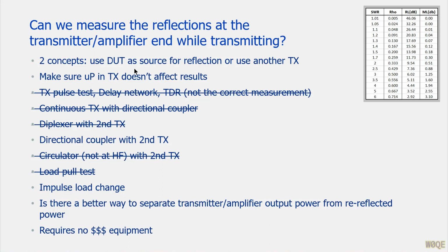And I wanted to do this without the microprocessor that's in just about every transmitter made messing with the output. Most microprocessors in transmitters are set to some limit. It might be SWR, reflected power. Usually it's reflected power, but I don't want the microprocessor messing with it. In most of the radios I have, the microprocessor also is involved with the initial waveform, and there's some leveling that takes place with the output, adjusting the power of the output slightly in the first fraction of a second. And I don't want this to mess with the results either.